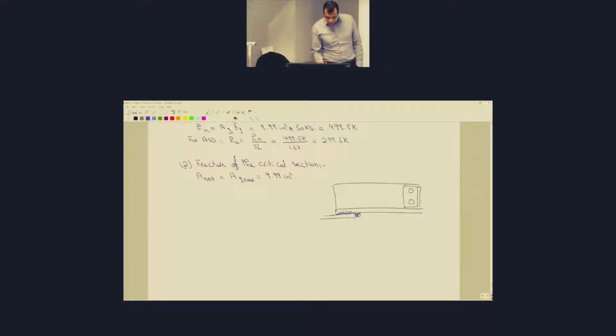You have, let's say you have this member, okay? It's connected here by weld, it's connected here by weld, and there is a transverse member connected to it, okay? This transverse member is connected here by bolts. So the bolts here are not transferring any of the longitudinal or any of the tensile load. They are just used to connect this member to the transverse member, okay? So although the bolts are not part of the connection of the element, they are actually a hole in the member, right? So there is no distance for them. It depends on the location of the other member.